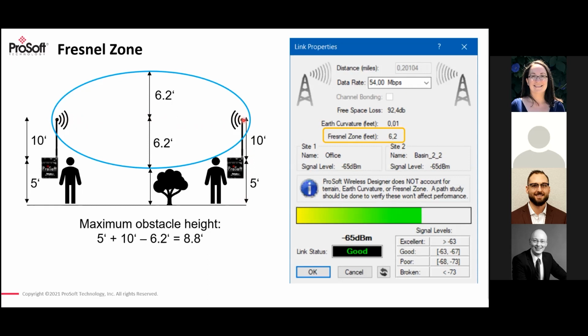So we need to consider something called the Fresnel Zone, which is kind of an elliptic curve between the two antennas. So instead of imagining just a straight line with the laser from one point to the other, we need to think of it as the waves for communication needing a bigger space. They need a little bit of space above the direct line in either way. In three-dimensional space, it's basically a big volume of extra space necessary for optimal communication.